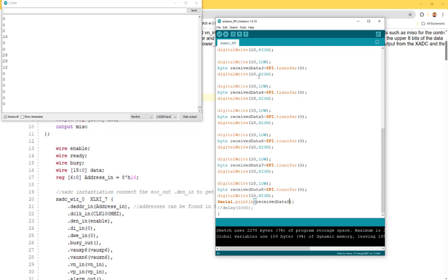Still do a lot of data acquisitions and eventually only take the 9th one. So do 8 data acquisitions. This is a CS pin or SS pin. It gets put down to low, or to 0, and then you do the data transfer and put it up to high. So that's the SS. Okay, so do it 8 times, and then you've got the 9th one, and transmit that one to serial. Okay, that's how we did it.